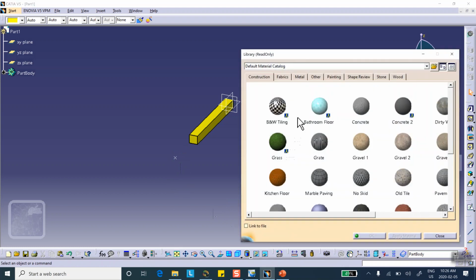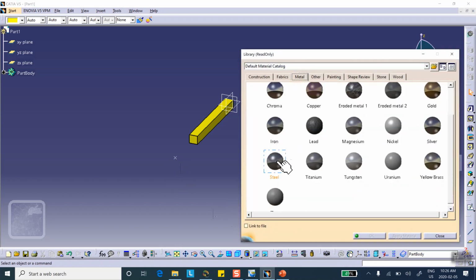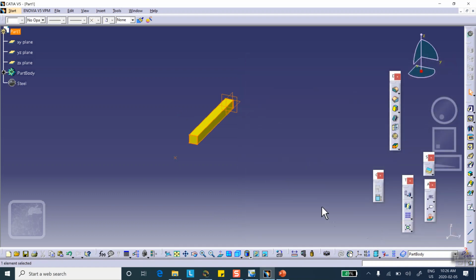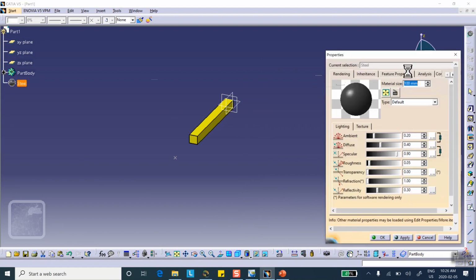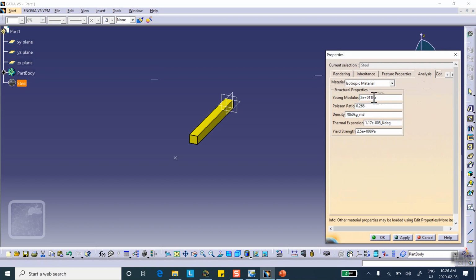Let's apply material properties on it. So metal, and I think I use properties of steel. Let's do that. Okay, just to make sure, let's go to properties of steel here. Default properties of steel. Notice that this is 2 gigapascal, and I'm sorry, is it 2 gigapascal? 200 gigapascal, not 2 gigapascal.